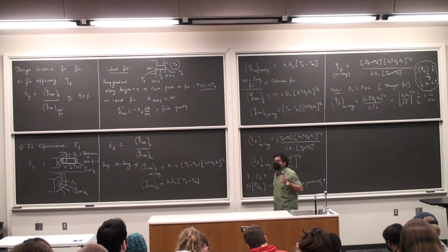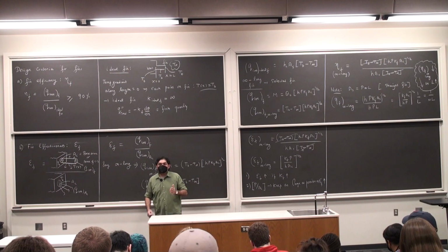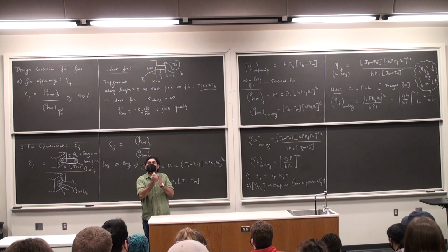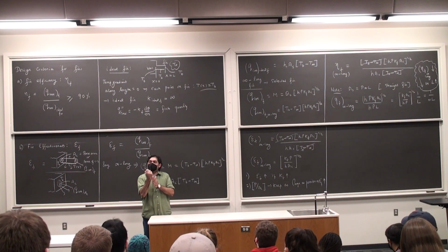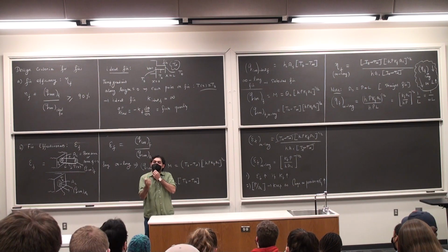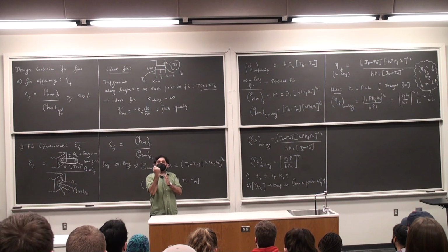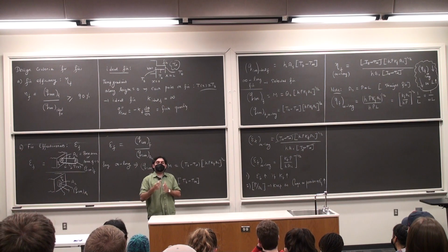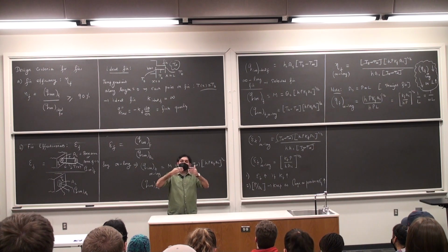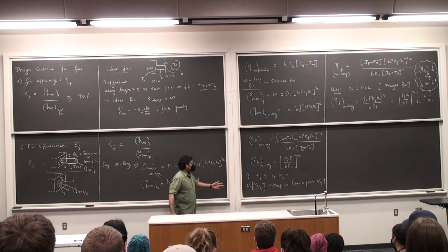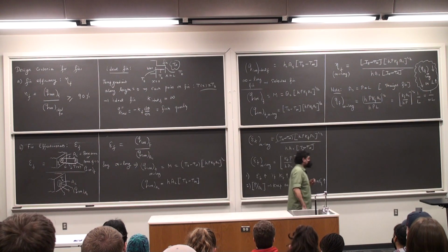And the consequence of this is most fins which are really effective are going to be either small, thin pins. If you look at a pin, the area of cross section is really small, so the ratio of the perimeter to area of cross section is actually a high value. Or if you look at very, very thin plates, if you take an IC chip, you're going to see small, thin slices present there, which are acting as fins, and that's because this ratio is maximized. So that's another added consideration.